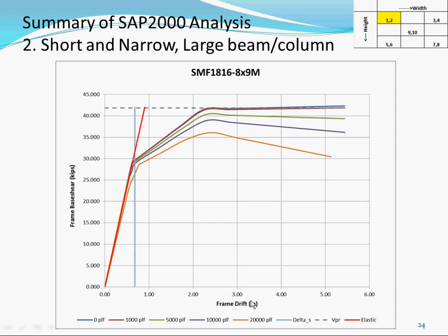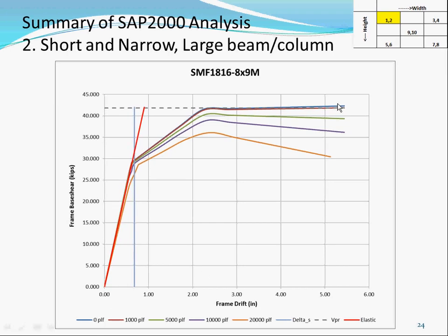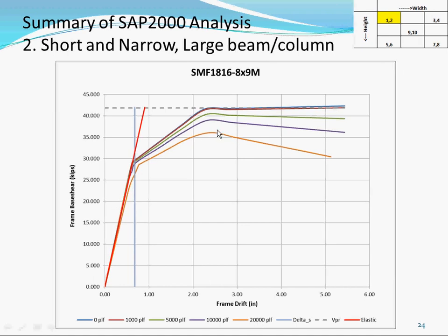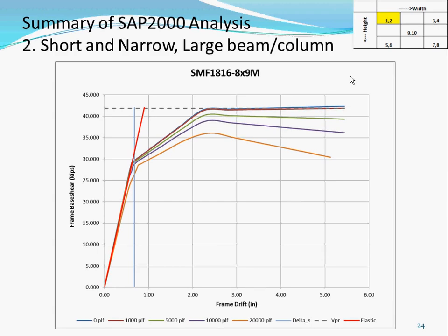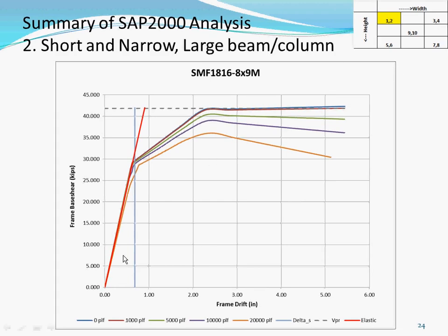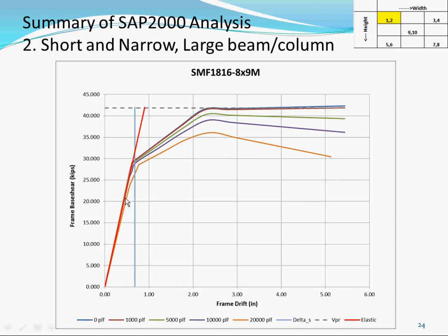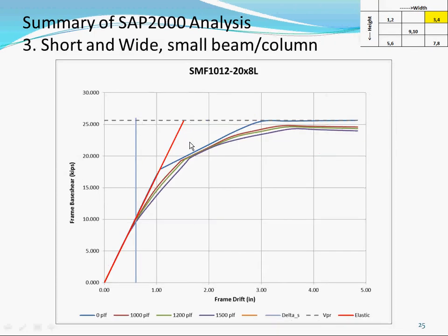Okay, so when you push over without any gravity load, you get the top curve. With whatever gravity load, not even maximum, you get this curve, and you also get a little P delta. That's where the P delta comes in. This is the P delta, because you're adding a lot of gravity load. It's starting to tip over, so you can see the difference. So we did a lot of study on making sure the design is elastic, and we don't go into the inelastic region. So that's all the analysis checked before.